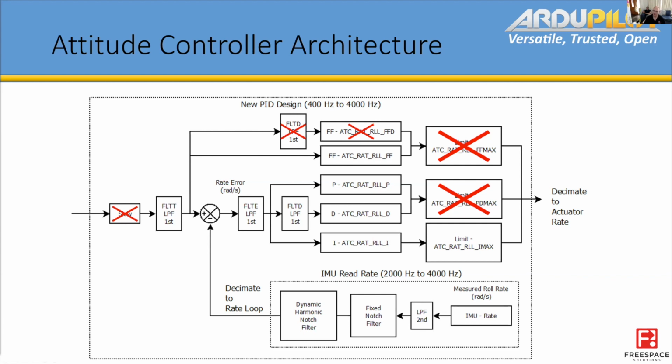And this is where, when I was talking about auto-tune, being able to just point at a particular set of these. So for example, yaw, we tune P, P is equal to I, and we tune this filt E. This is set to 0. This is set to 0. For the PID, we tune PD primarily. I is equal to P. Your I is 1/10 P. Roll and pitch, we tune P and D, and these filter settings need to be set by the user.